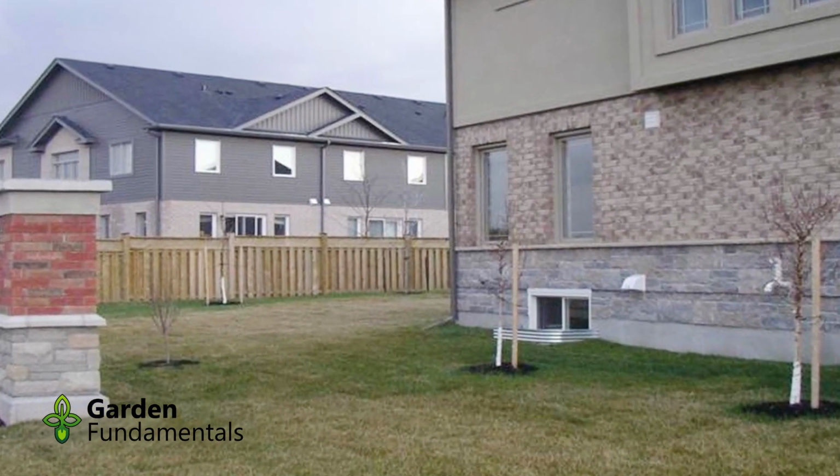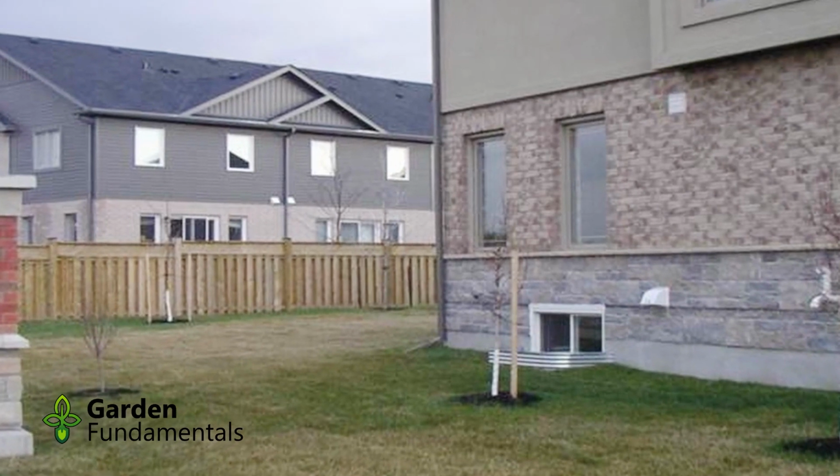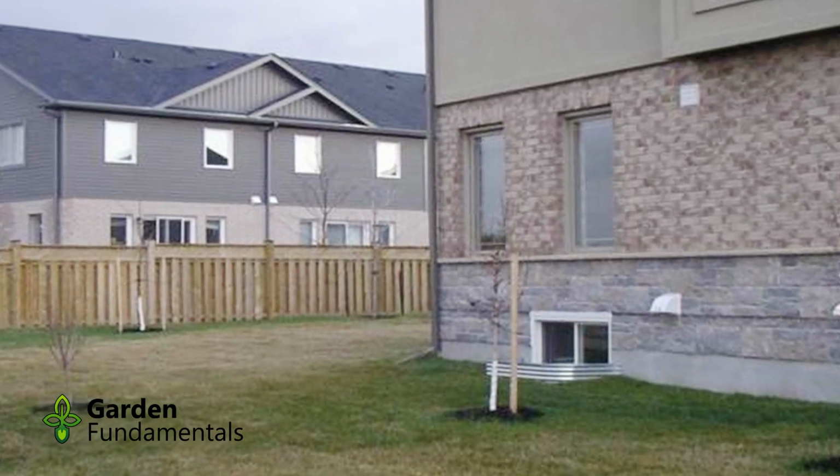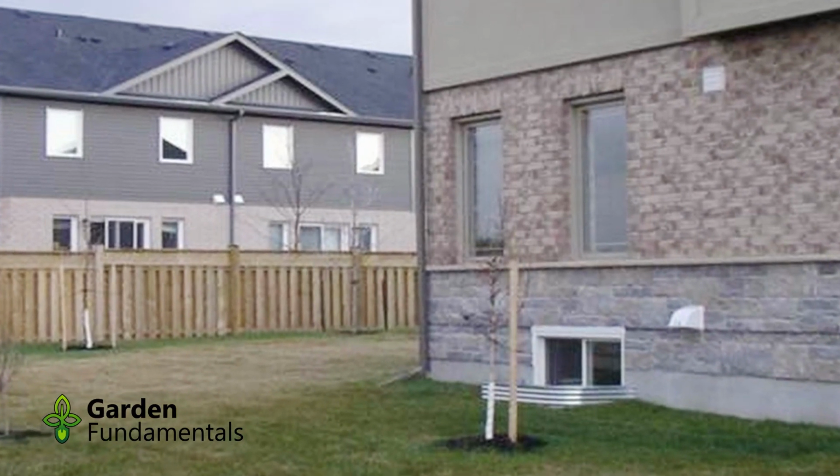You'll notice that the back corner of the house has a basement window with a window well around it. We're going to have to take that into consideration because we don't want to block the light from getting into the basement. So we kind of have to leave this area open. We also don't want to remove that metal that's around the window. If we do that, then we might have a drainage issue with water running into the basement. So when you see something like this, it's best to just leave it alone and do a design around it.